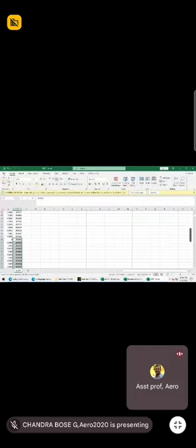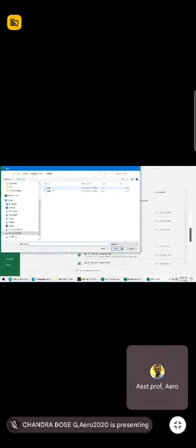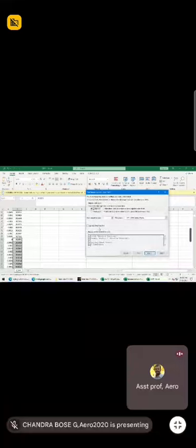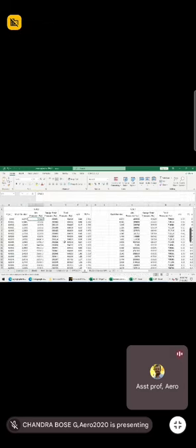So you can see there, File, Open, browse. You can open the CLSP, you give yes, next, semicolon, comma, space, next, finish. So for the same case, you will get the center line static pressure. So you copy the static pressure from here and paste it in the base file. This is absolute pressure. So you paste the static pressure here.